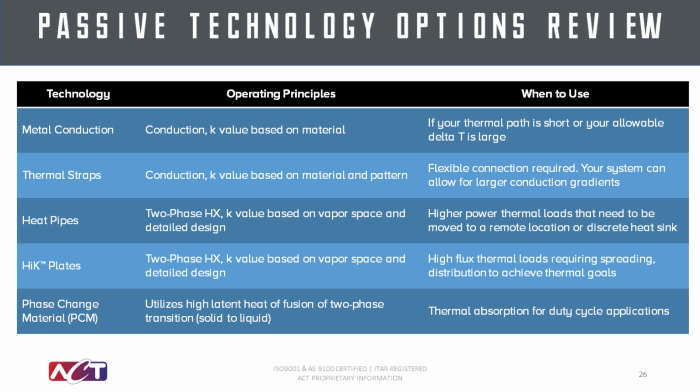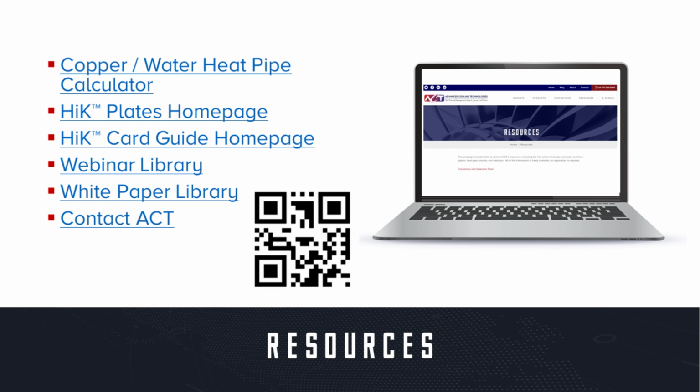And finally, in transient thermal load applications, phase change material can be integrated into these heat sinks in order to dampen the load, such that now you can design the system for the average power instead of the peak power, and or they can be used to simplify the design of the thermal solution in one-time use devices.